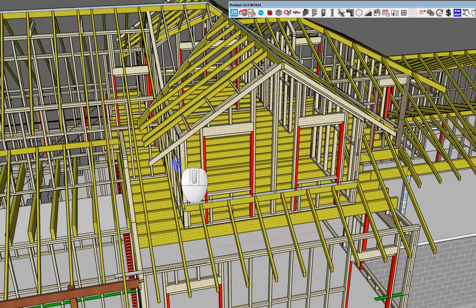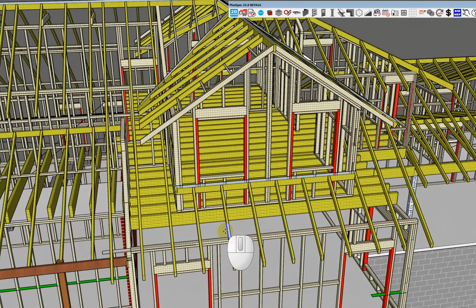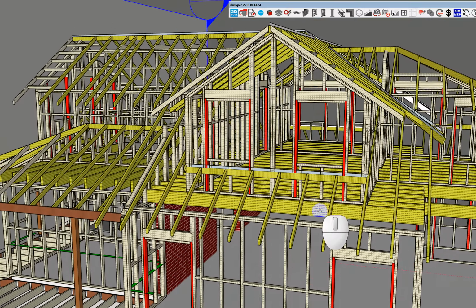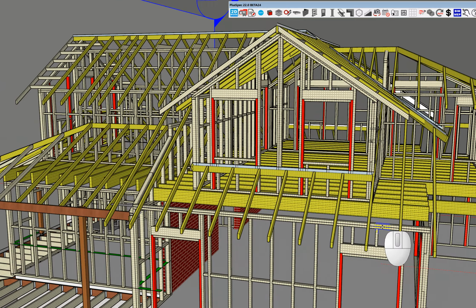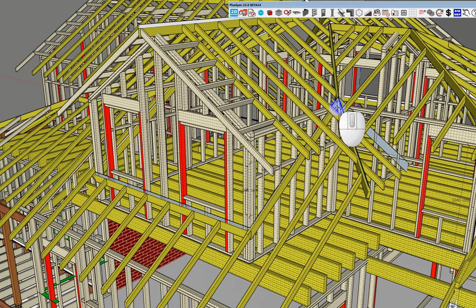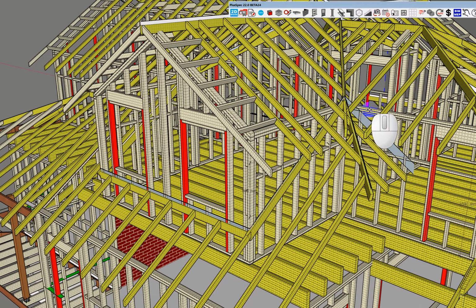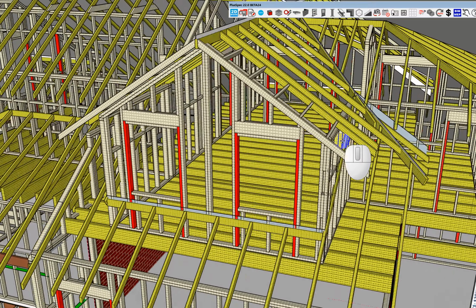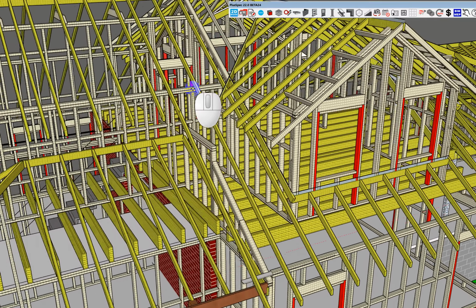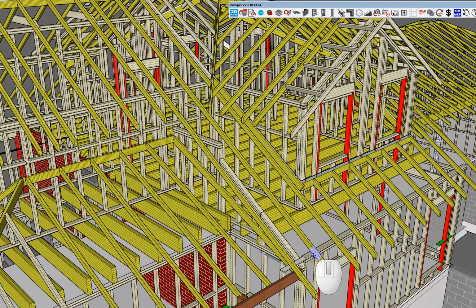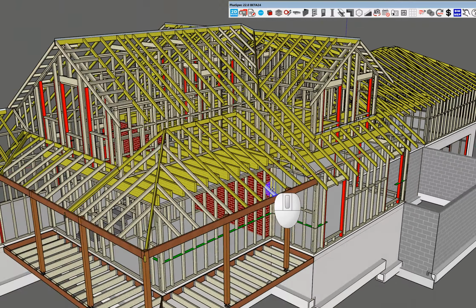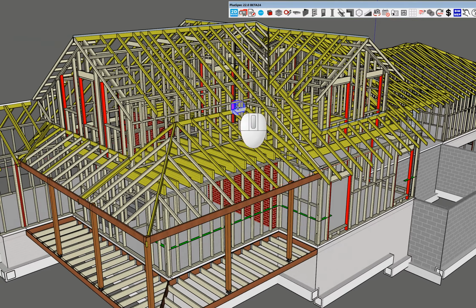Also, you'll notice that these walls here are load bearing over the top of joist span. So there's a fair bit going on here. And also this wall here is lining up so that this rafter lines up with that roof line as well. So it's kind of complicated. Same would happen here. The height of this wall here is dictated by the height of this wall and the pitch of the roof. So let's have a look and see if we can run a section through there. I think that might help out a little bit.